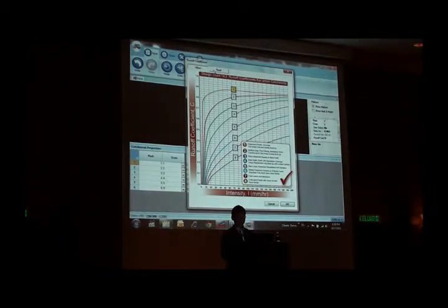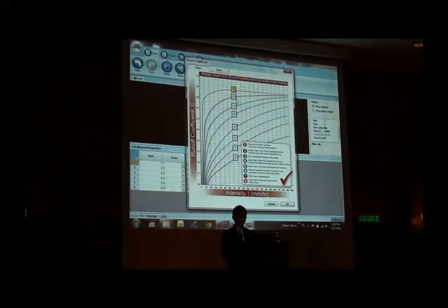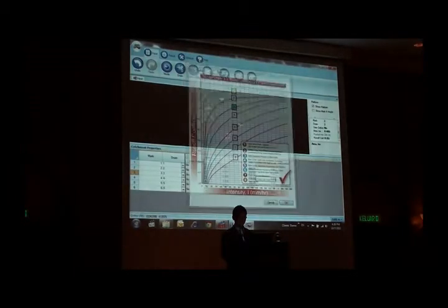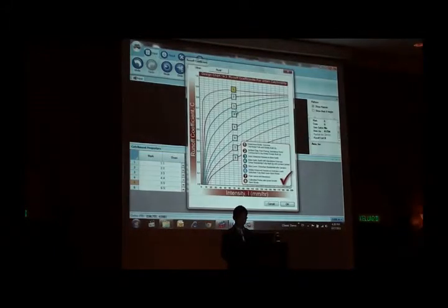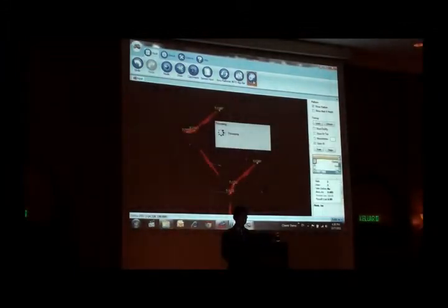We can choose whether it's urban or rural area. Let's say urban, type number 2. The second one is urban, type number 3. All this follows MASMA. Maybe the last one is type number 8, pervious area, so the coefficient C is 0.55. That's all we can analyze.